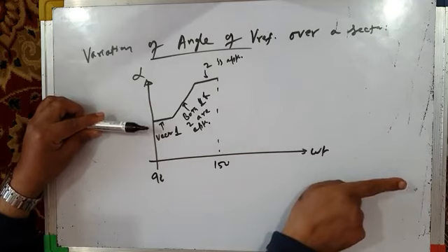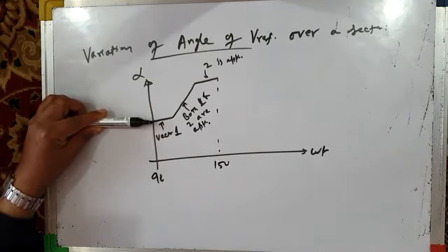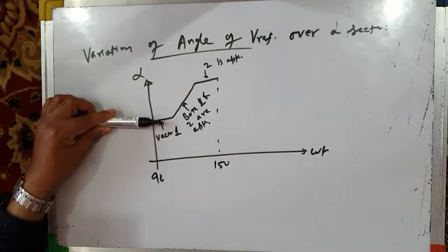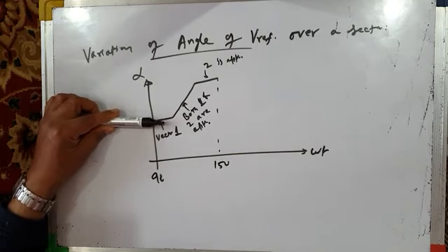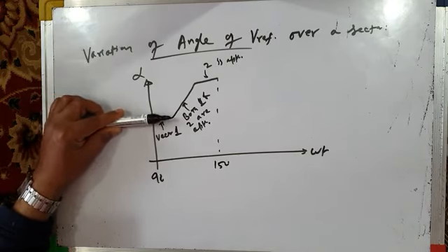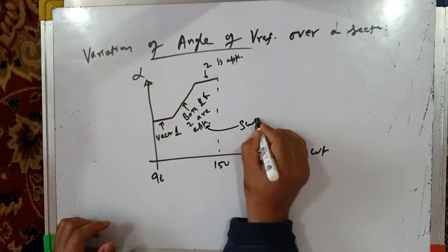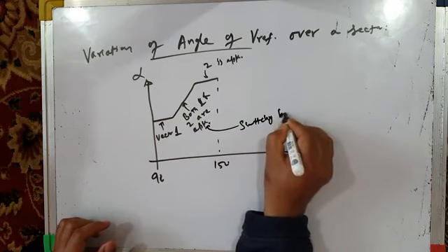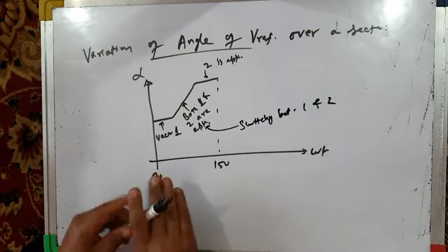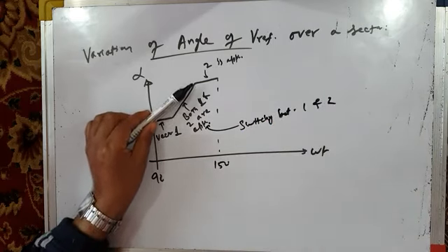Okay, it starts from, say, alpha rotating, and then it stays at active vector 1 for fairly long time. That means alpha does not change. It remains constant. And then there is switching between 1 and 2 active vectors, and then angle increases linearly.